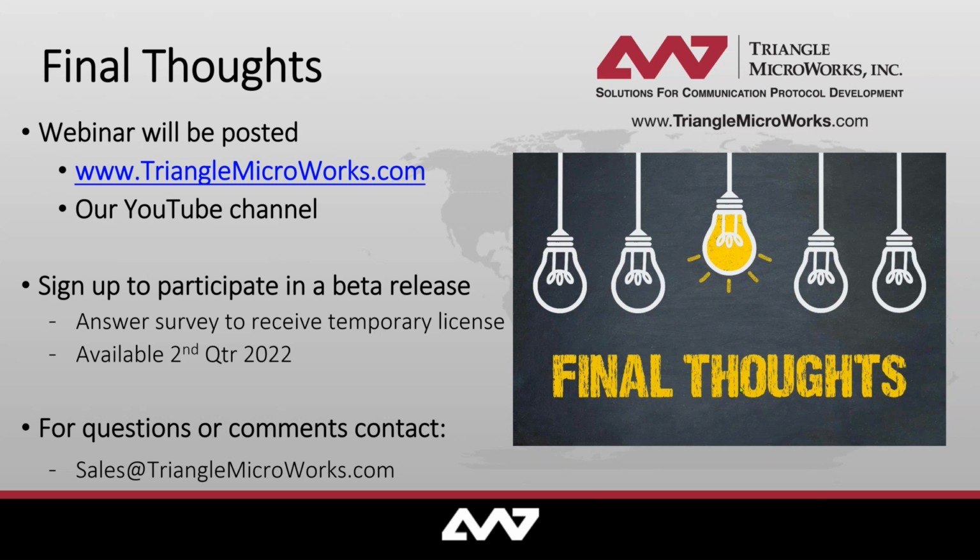The second parameter would be protocol dependent. For 61850 or TASE.2 ICCP, it will be a path, the MMS path or the 61850 path, to identify the attribute in that case. For DNP or the other protocols, the second parameter might be an object ID. So the object index, or I guess for 60870, it's the request ID that you use to identify that. Finally, for the point-based protocols like DNP, 60870 and Modbus, the third parameter would be a point index.